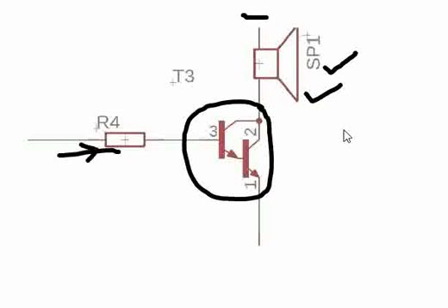This is how we generally use the Darlington pair in audio applications. Second, it can also be used as a buffer, because it has a high input impedance and low output impedance. With high input impedance, the simplest advantage is that the input current is low.